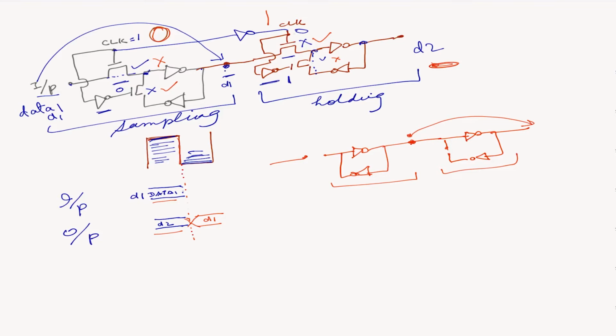Now you can take a look that this is where the change happens, on the fall edge of the clock. So it's a fall edge flip-flop. Some flip-flops depend on where you put the main inverter for the clock. So you can also make them transition the other way, where data transfers on the rise edge of the clock and doesn't change on the fall edge. Okay, so hopefully that explains the functionality of a flip-flop.